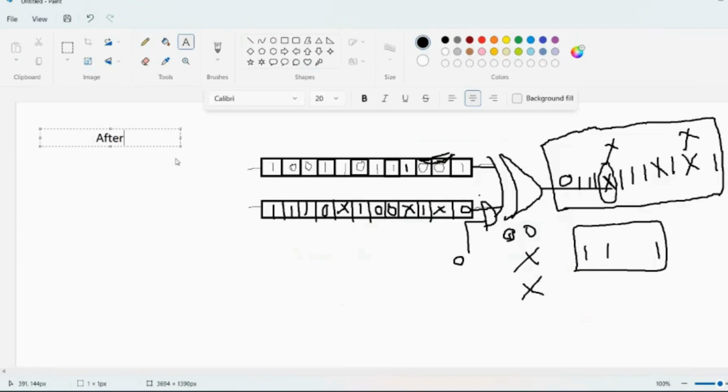So after scan insertion is completed, you write out the scan DEF file, SPF, and what we call the STIL file. SPF will automatically have this, right?